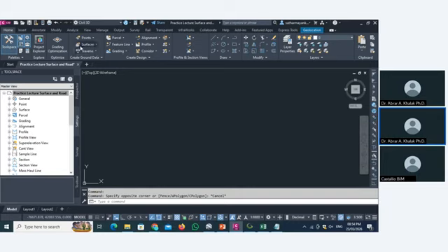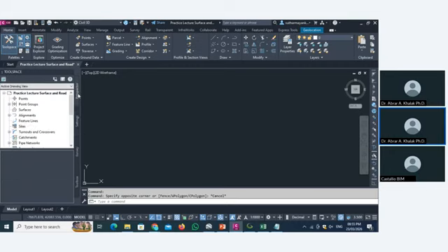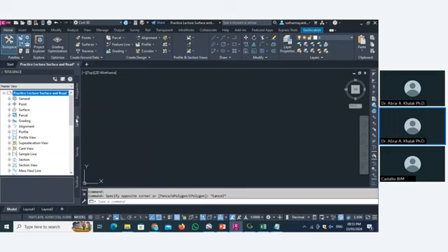These two are very basic. Whatever work you are doing in Civil 3D, whether from the infrastructure field, the railway field, or the utilities field, whatever field, you have to use these panels. If you are a master of this tool space, 30-40% of the work is almost done. We do all the work from this Prospector tab. If you want to change any setting, like for a point, you come here to the Settings tab and you can manage all the settings from here.